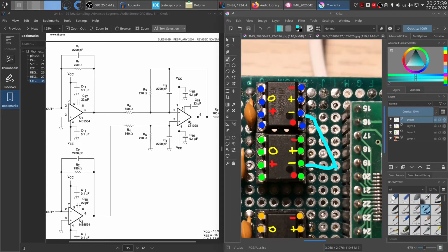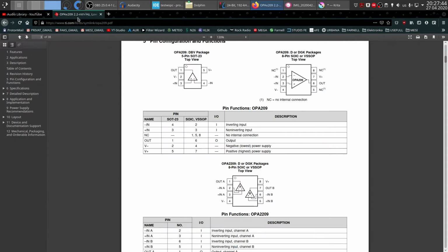So these are single amplifier packages. So it's very straightforward to use them if I just plug in the datasheet for an amplifier I'm looking at. Amplifiers can come in single amplifier packages or dual amplifier packages. So it's the same package, same pinout or similar pinout, but it can have one amplifier or two physical amplifiers inside. And there are two reasons why I would prefer single amplifier. The one is that very good amplifiers tend to come in only single amplifier per package. And although this one is a very good amplifier, it also comes in two.